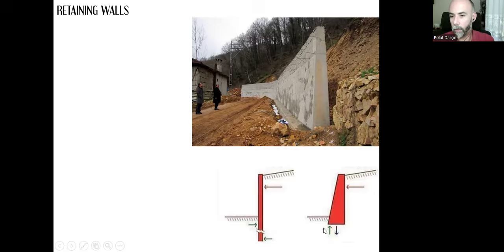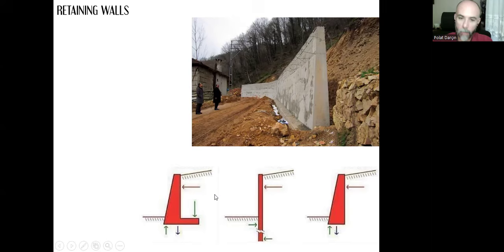Or instead of creating that sloped surface, we can go deeper and deeper. And with this depth, there's this load in this direction. However, because of the depth, there will be some counter loads of the earth. It will hold. Or we can have a footing for the wall like that. It goes in the other direction, and with the weight of that earth, again, it will hold. It will become harder for the wall to collapse down.